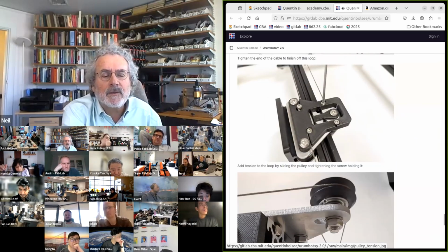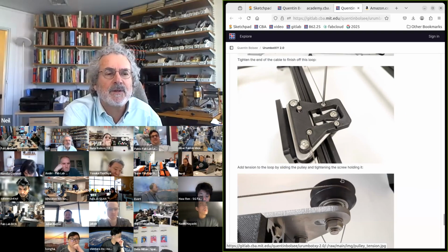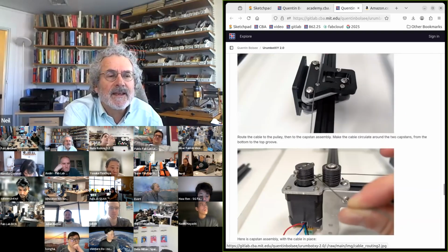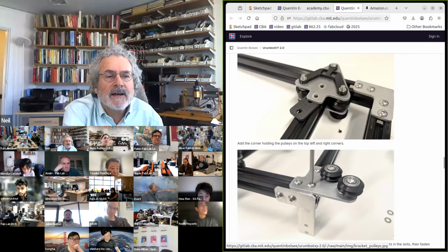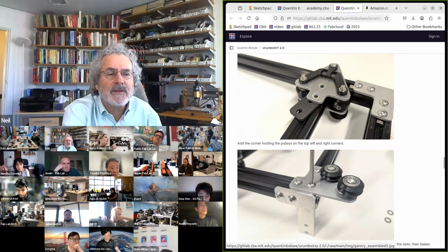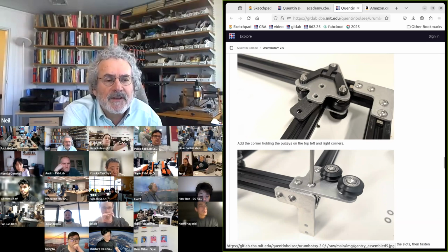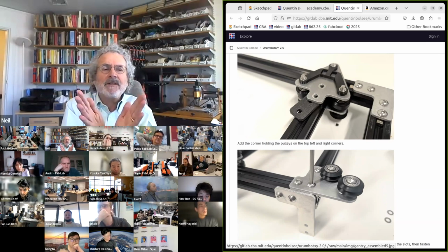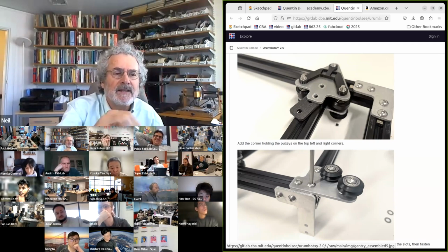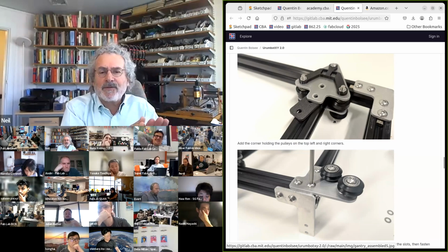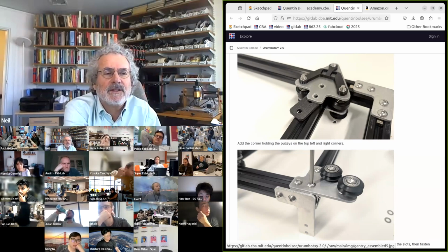this is a V-wheel where he's getting the bearing and it comes mounted in a hardened plastic that he's using to route the filament. And then for the carriage, if we come up to here, he's using now instead of the V, this is the tapered wheel I was looking for, and then the tapered wheel fits into the extrusion. You can get special extrusions that have angled faces specifically for this. If you use just a linear extrusion, there's a little bit more friction on the bearing, so the wheel will wear a little bit faster. It depends on how much load there is in the machine.